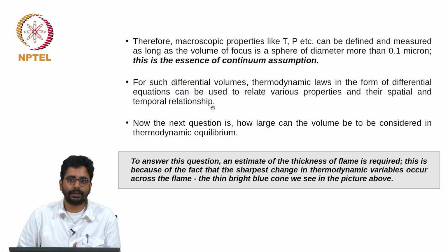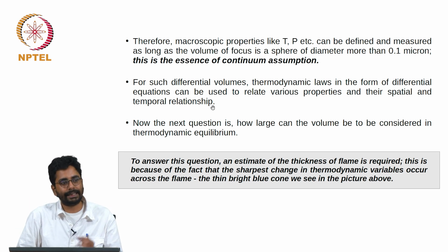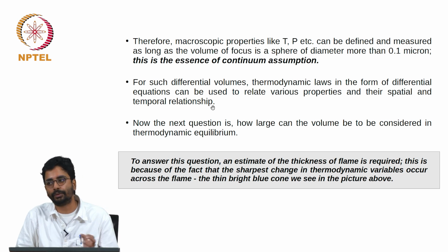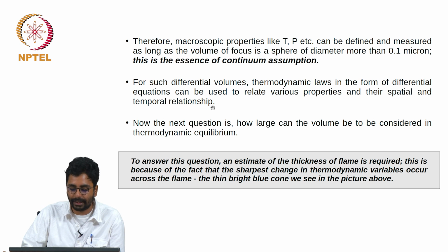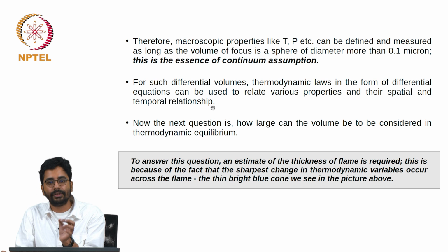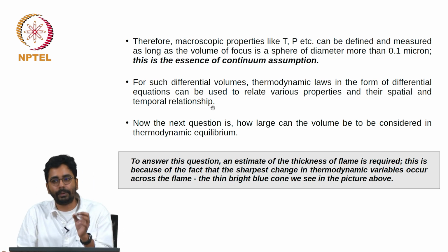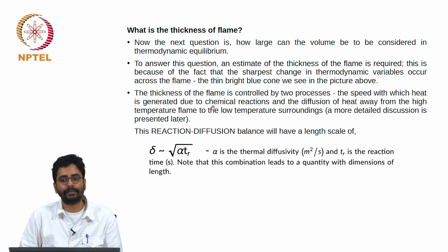The thin bright blue cone we saw in the picture in the previous slide, the thickness of that entity is the thickness over which the variables change significantly, and therefore we need to make sure that the volumes that we choose are smaller so that the changes are not large. So a good measure of that size is the thickness of the flame. So what is the thickness of the flame? That is the next question.